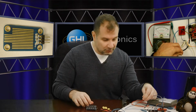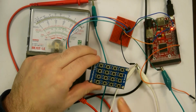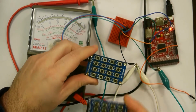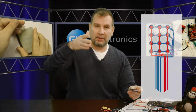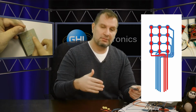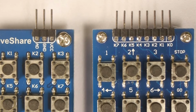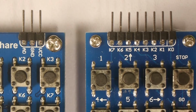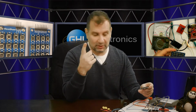And this is a pretty sweet example. This over here is basically a matrix of buttons, a lot of buttons. And this is the exact same one, but this one is done through a matrix. We had another tech talk where we talked about matrix and how you would have columns and rows and how you would scan through them to reduce the amount of pins you need. So over here, there are many buttons. There are fewer pins, they are connected like columns and rows, and this is how you get fewer pins. But then you can reduce this to just one pin, one analog pin, and that's what we have over here.